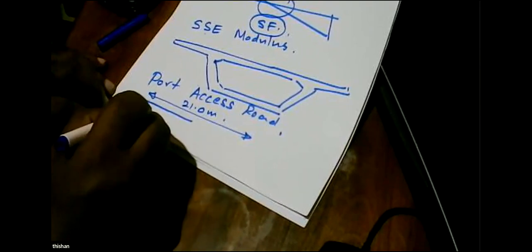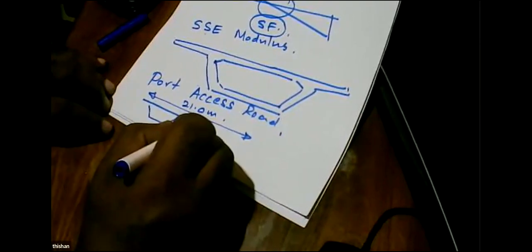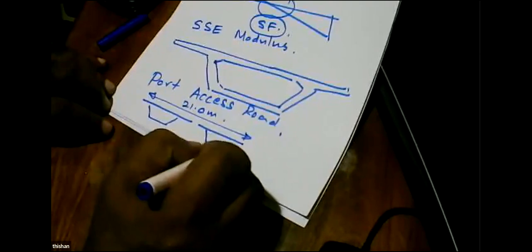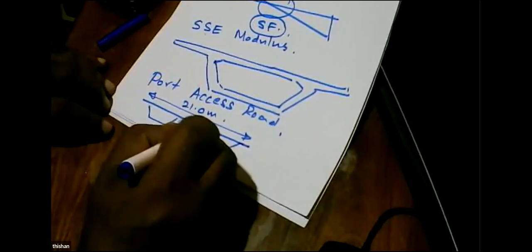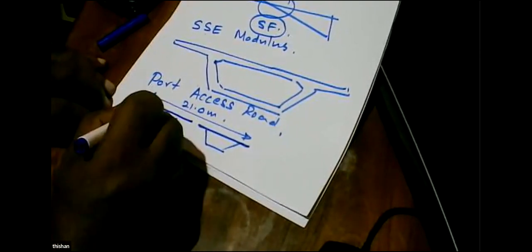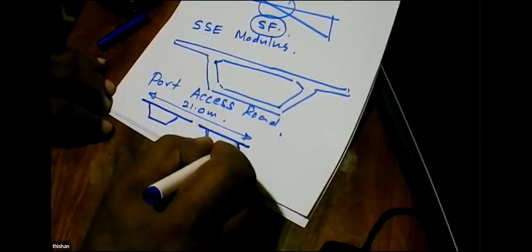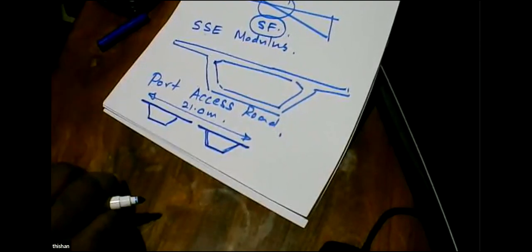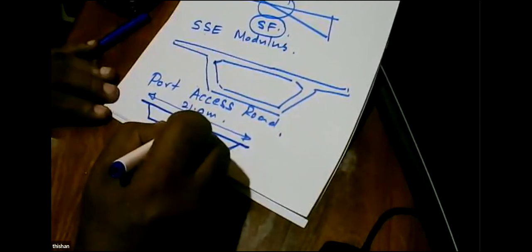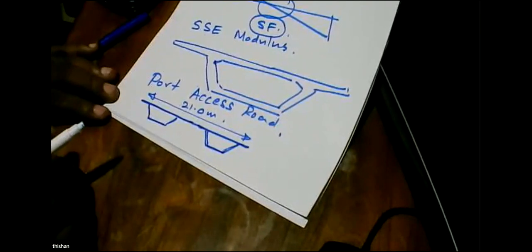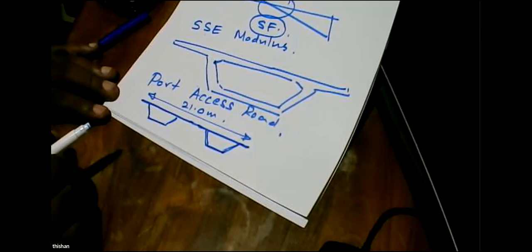Two box girders have been used by this Hong Kong-based designer, and the role of the Sri Lankan team was to see whether they are okay and coordinate. The actual design came from Hong Kong, and they used two box girders, and the construction method was a segmental match-cast segmental bridge.